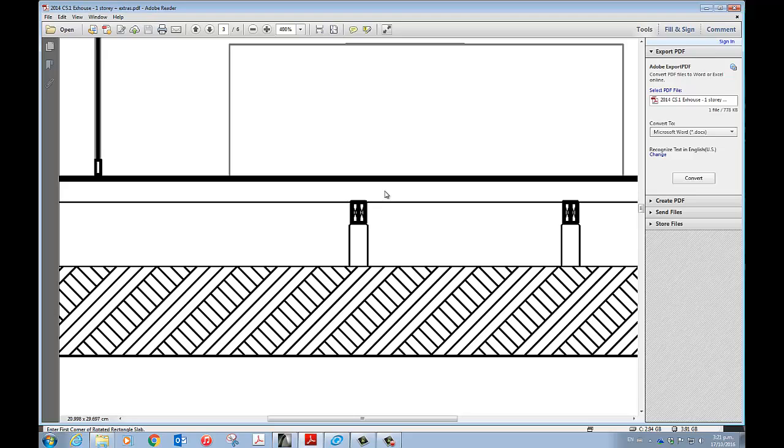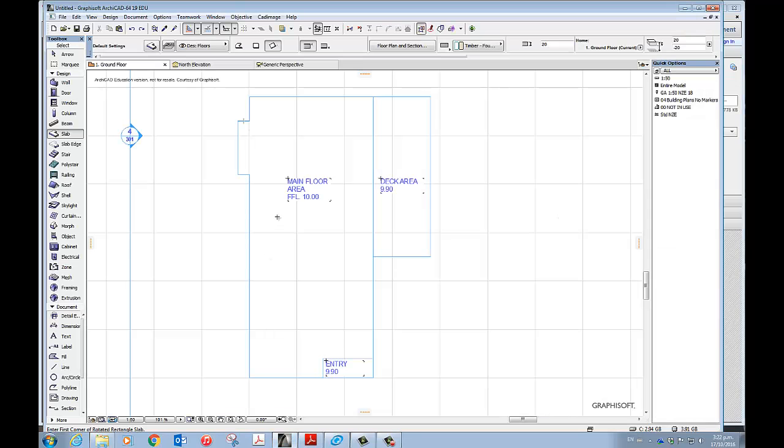When we model the joists, we have to remember to set them down 20 millimeters below finished floor level. And when we model the bearers, we've got to add on 20 mil plus the depth of our joist, which I will just be estimating in this exercise. You people should use 3604 to design the subfloor and be able to explain that at the end of your interview. Okay, back to Archicad.